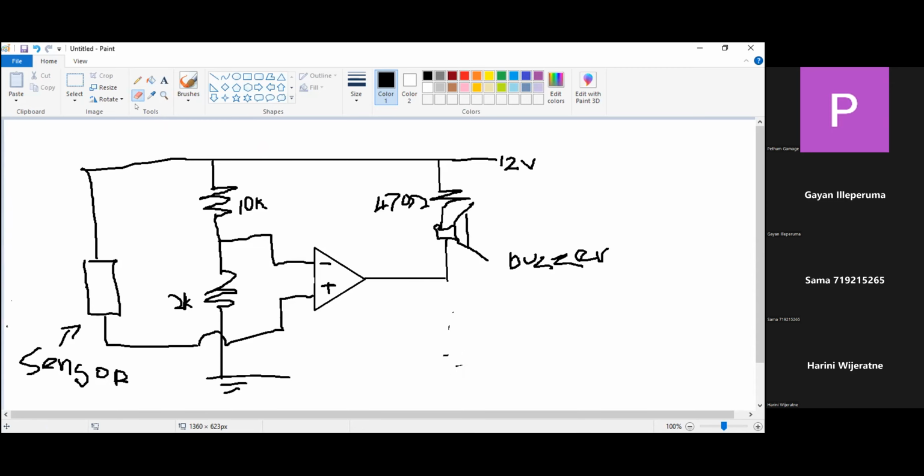Because the pull ups and pull downs are there because you don't draw any current, but you are sensitive to its voltage. So if you have any charges left, your sensing IC, logic IC can detect it as a voltage. We don't want that. We want to make sure it has only 5 volts or 0 volts. So that's the purpose. But if you already have a current output that can drive it, then you don't need to have pull up or pull downs.